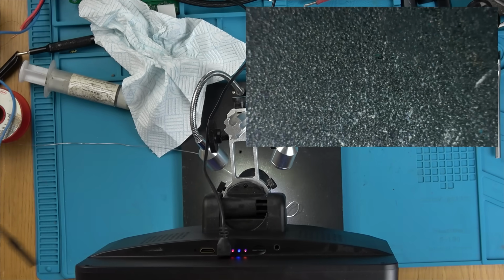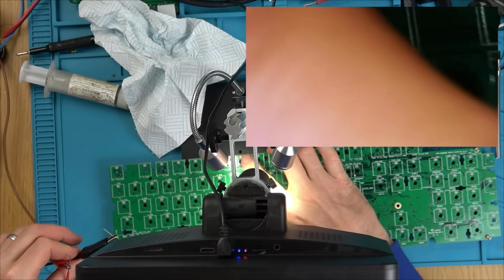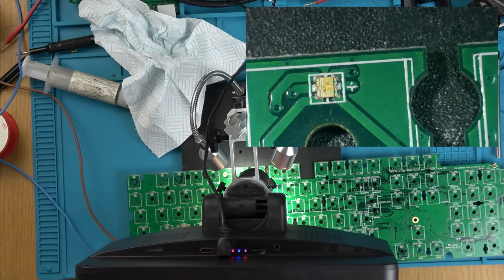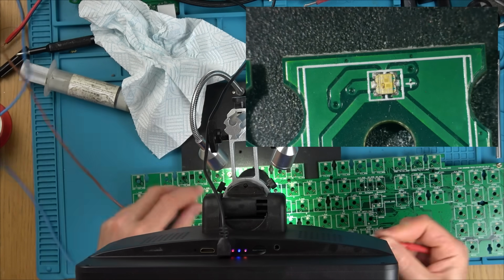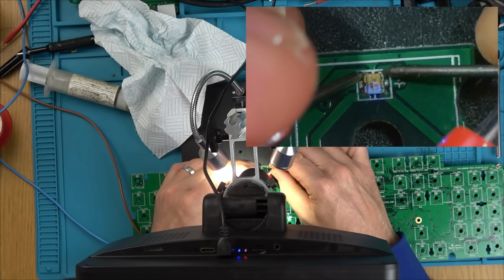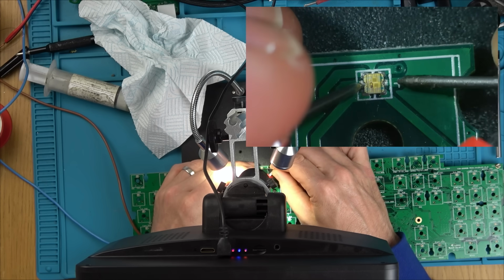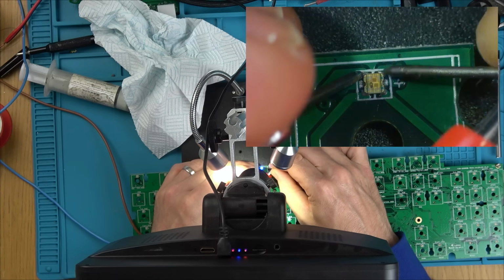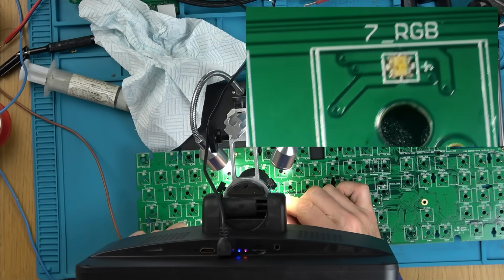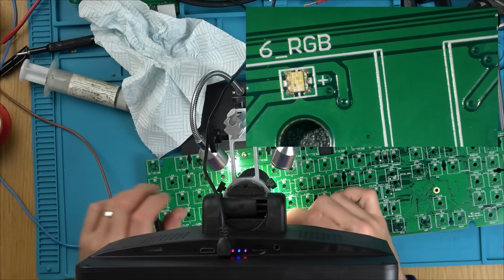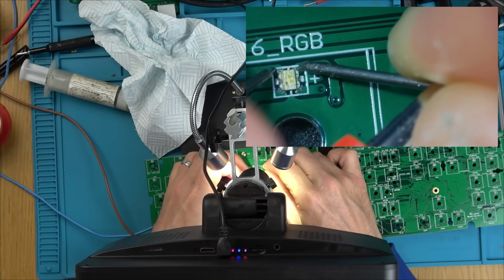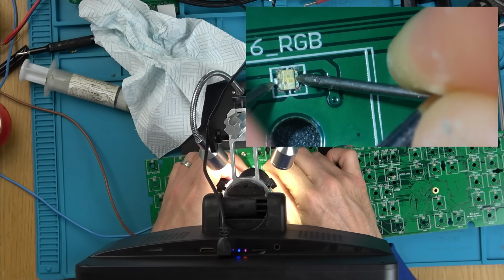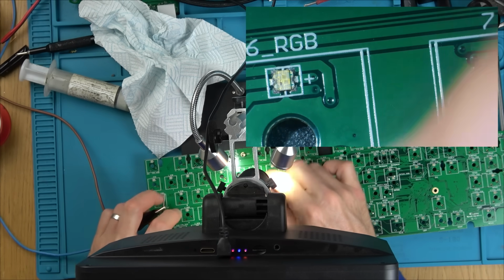I just want to go up to one of these ones that are just lighting up cyan, this one here. Let's just see if this one is lighting up all the colours. Then we'll sort of know, is it the LEDs or is it the data feeding them? Blue, green, red. Okay, so it is actually working. And then it was, I think it was this one here. Green, blue. I'm just going to tap it quickly. There. Yeah, okay.